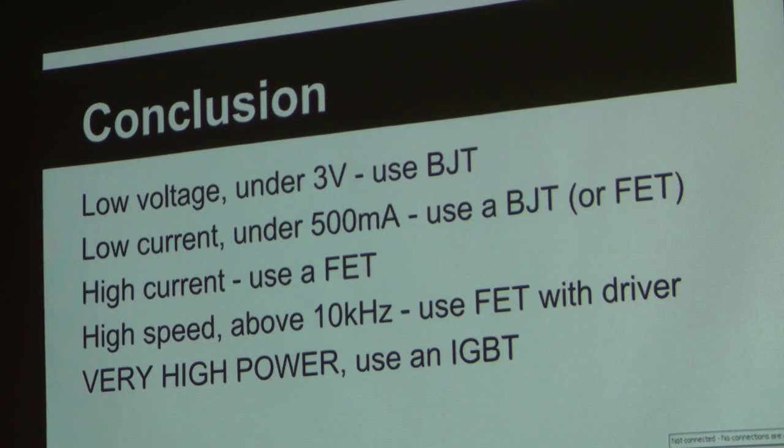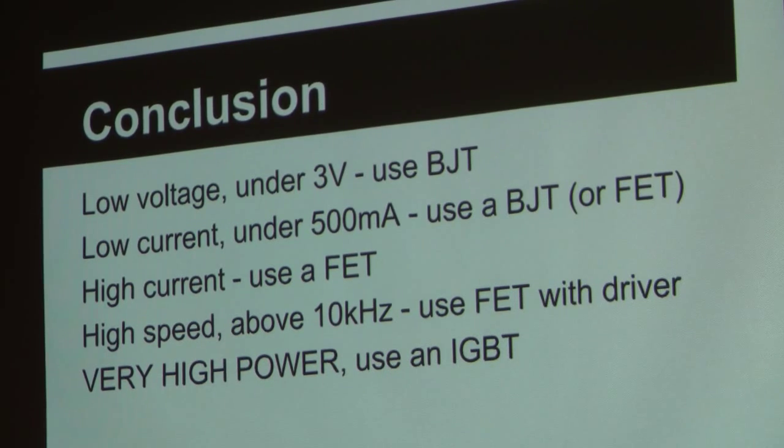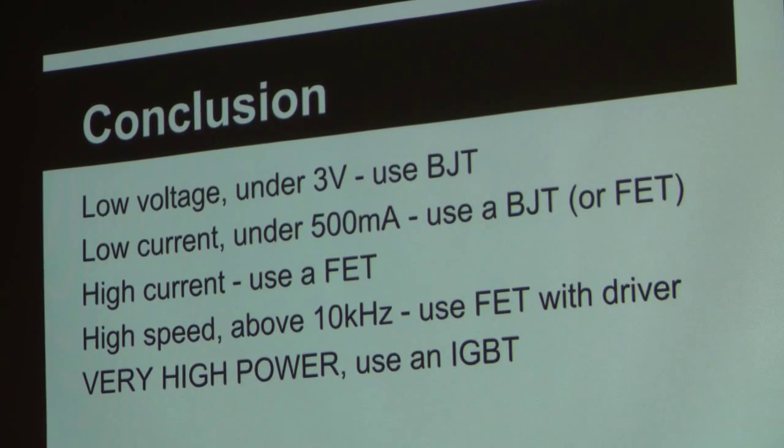High current, definitely use a FET. If you're wanting to switch 20, 30, 50 amps, there are MOSFETs out there that can do it, if you use the proper wiring, proper board layout, proper driving. We'll hit on some of that. FET, oh, I'm sorry, field effect transistor, MOSFETs. When I say FET, I mean MOSFET, metal oxide semiconductor field effect transistor. And there's like 6 different kinds, but we're really talking about enhancement mode. I'm only going to touch on one. And mostly I use NFETs.